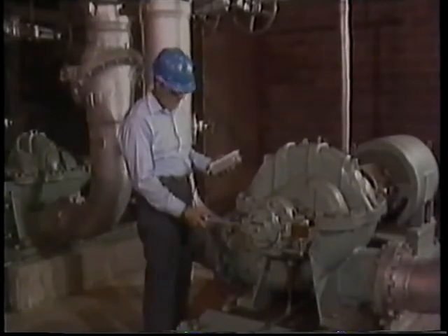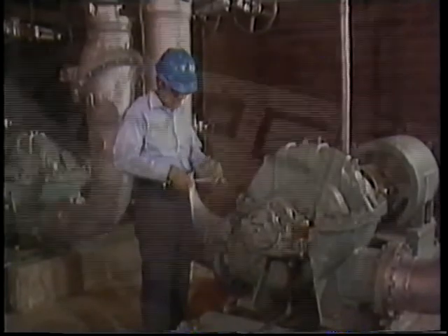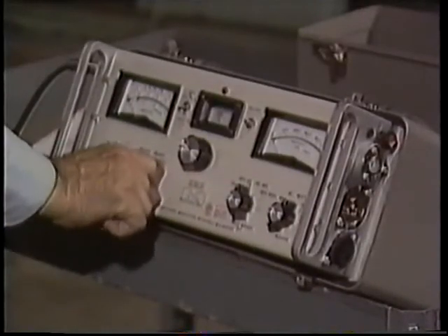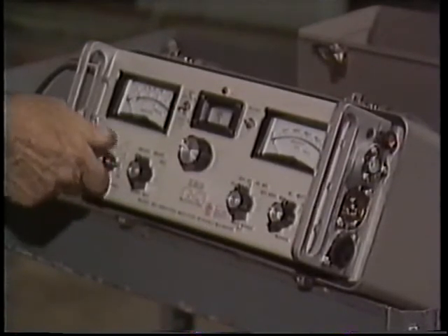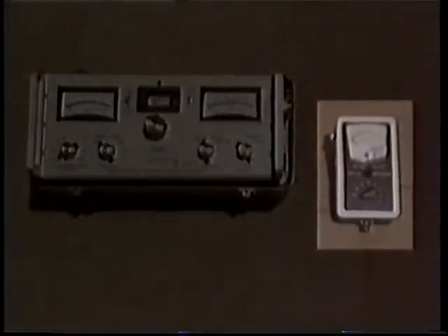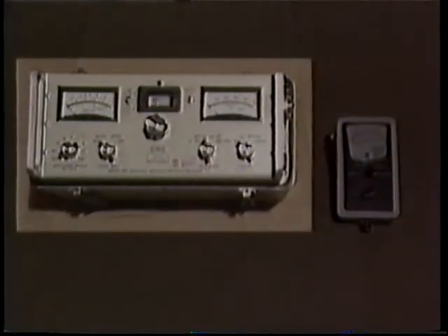Monitoring vibration amplitude can alert you to the presence and severity of a problem. Analyzing vibration frequency gives you the basis for determining the cause of the problem. A vibration meter can only measure the amount or amplitude of the vibration. But the basic function of a vibration analyzer is to pinpoint the frequencies at which high vibration amplitudes occur.